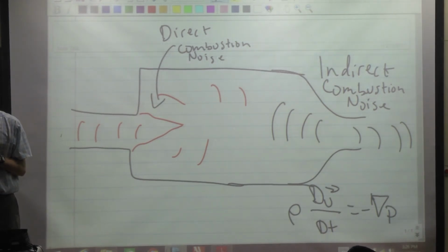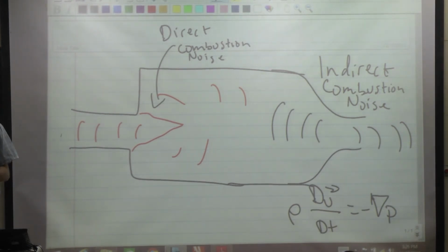So suppose that the density of what I'm accelerating through the nozzle is not constant. It's changing. Well, if the density is lower, to do the same amount of acceleration, it takes less force than if the density is higher, for instance, right? Now imagine the density is oscillating. So the density is not constant. It's going to require a time-varying force to shove that through the nozzle, right?